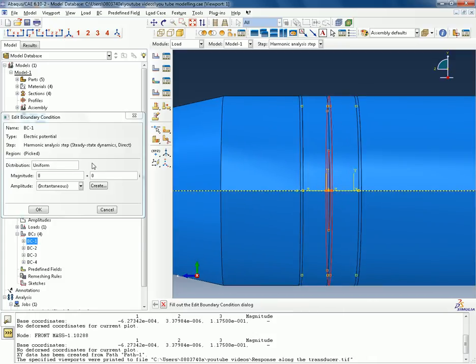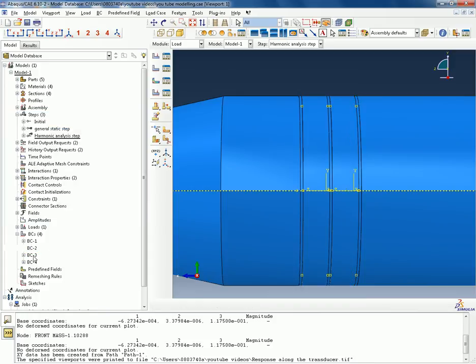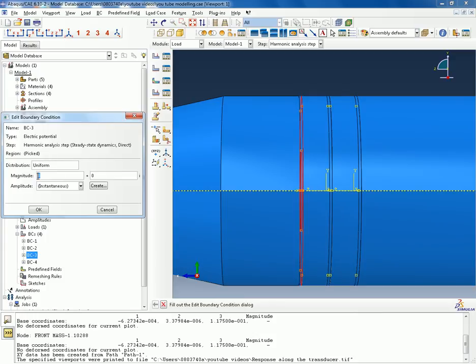Now the checking has been completed, and as you can see, we don't have any errors. You only have a number of warning messages, some of them relating to the output requests, which cannot be considered in this analysis. If you wish, you could remove these requested parameters. We'll go back to the output request and check which ones you selected.